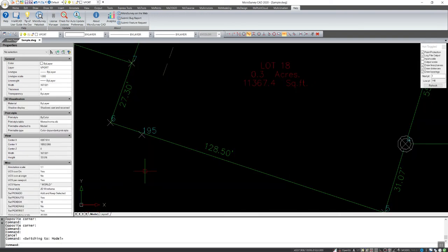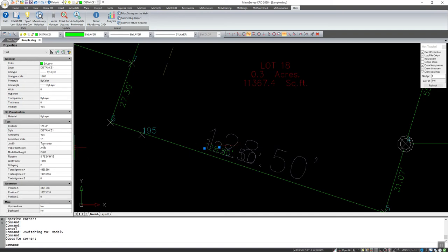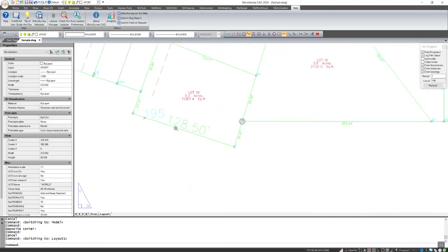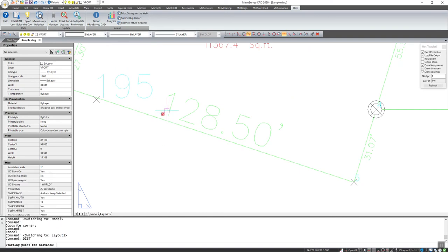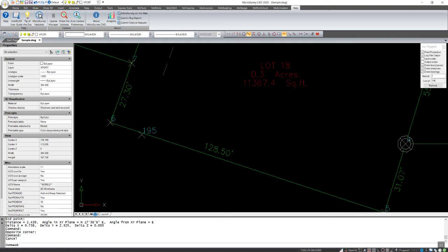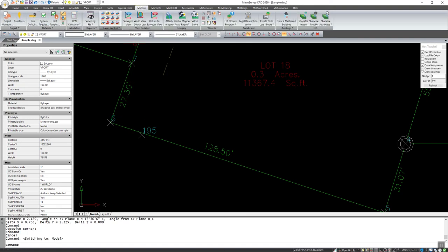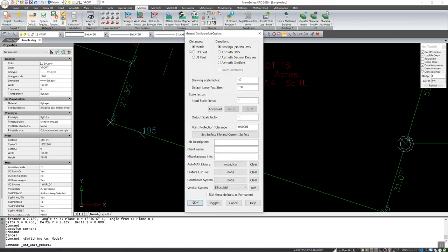So if I go back to my model space and look at this text, it has a paper text height of 2.4. If I go into my layout, I'll just do a distance check, snap there. I'll just do a rough distance check here. So with distance roughly 2.4. I didn't snap to the top of the text, so it has a size of 2.4. So this is a metric drawing. If I go to my job defaults, metric.